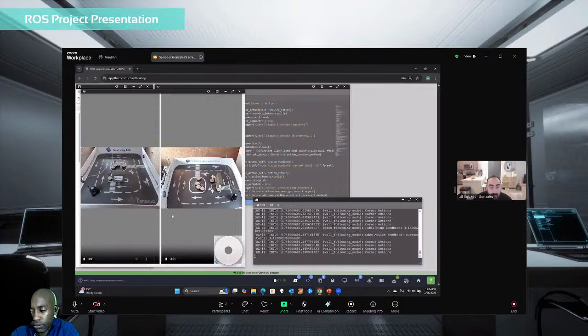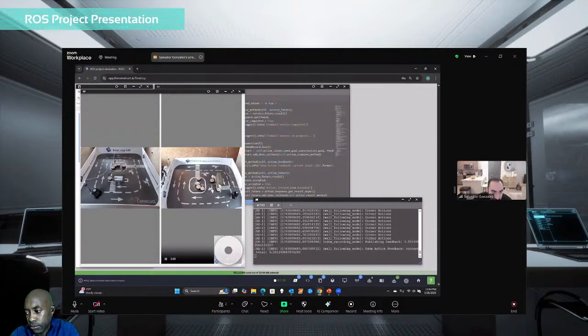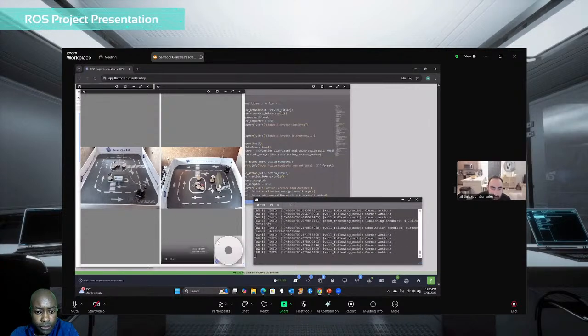I have a predefined curve that I experimentally determined was an appropriate curve path to follow. Once it exits that, it will return to the wall following behavior. The wall following behavior is a combination feed forward proportional controller.